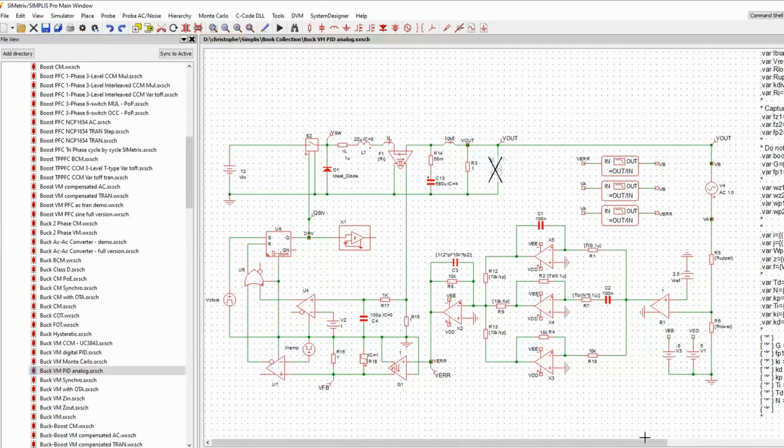When you tweak a PID on the bench, and usually it's the case with digital control, you can apply several methods, like Ziegler's method, for instance, where you more or less reduce the Ki and Kd coefficients to 0, then increase the Kp coefficient until you start observing a ringing response. It's a kind of trial and error method.